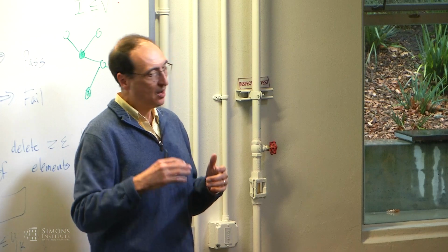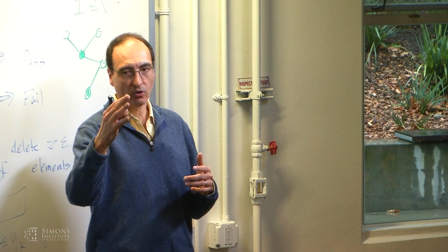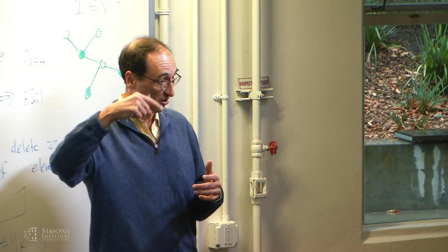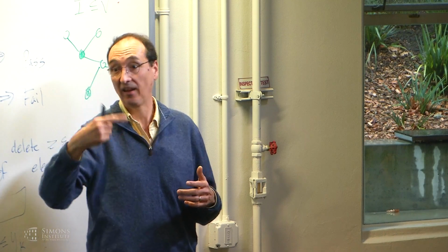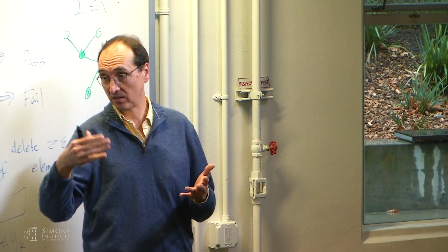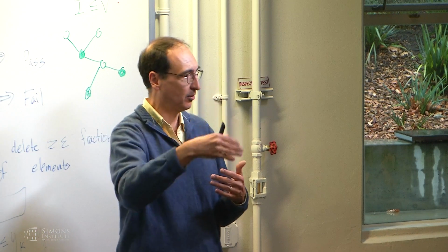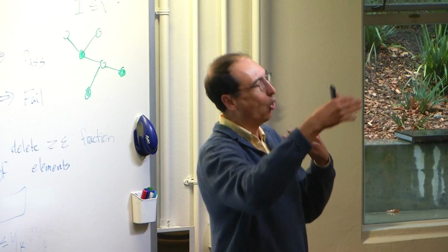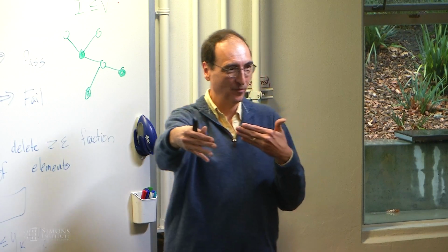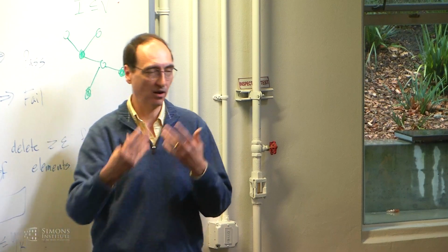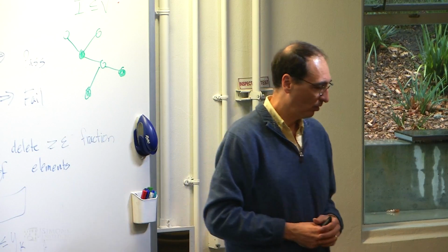You might say, I'm going to schedule when those chillers are going to turn on, but then I'm going to modulate the load on the chillers. That is, which chillers turn on, how many I turn on. I might do that once a day. So I just say, hey, it's a Wednesday, it's going to rain, so I'm going to calculate out, I'm going to turn that chiller on at 2 o'clock, and then I'll turn this other one on at 4 o'clock. Sometimes that's an open loop once a day calculation, because it might be easier to do, or your software doesn't handle it, or you don't want to start and turn on and off chillers and things like that.